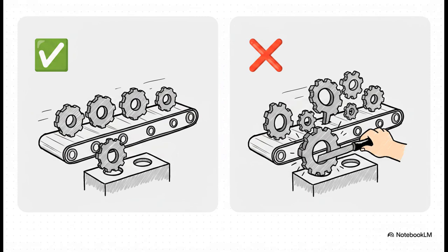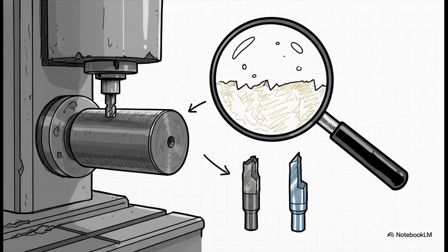We're essentially looking at two very contrasting realities here. In a world of low manufacturing variability, highly consistent processes mean parts fall right within specified limits, and universal interchangeability totally thrives. But if you introduce high variability, suddenly parts just don't fit. The exact moment a part is too large or too small, boom, it loses its interchangeability. It suddenly requires manual modification, like filing or machining on the spot, which introduces a huge risk of failure and completely bottlenecks production.